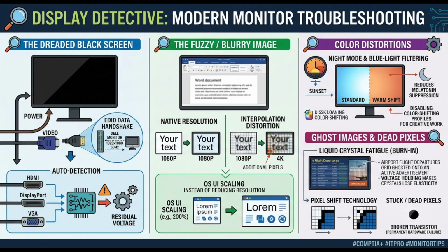And this leads to a crucial operational rule outlined in the sources, the necessity of the graceful shutdown. We have all been in a meeting that runs long. The second it ends, someone just yanks the projector's power cord out of the wall so they can pack it up faster. Why is that such an expensive mistake? Because you are completely disrupting the thermal management cycle. When you rip the power cord out, the cooling fans stop instantly. But that glass bulb is still radiating 1,000 degrees of heat. Oh, right. It doesn't just instantly cool down.